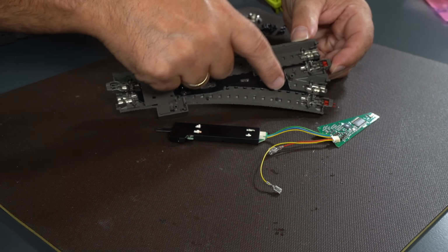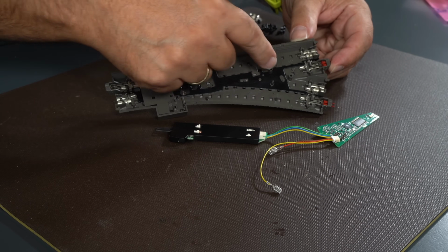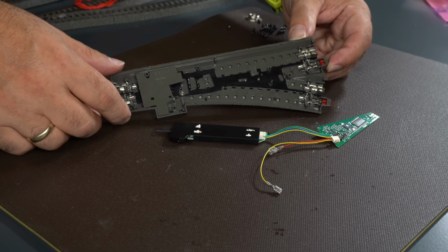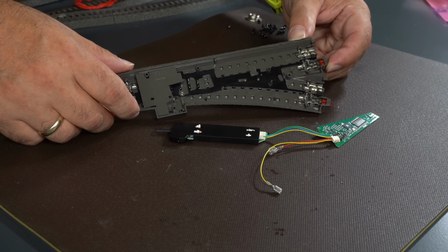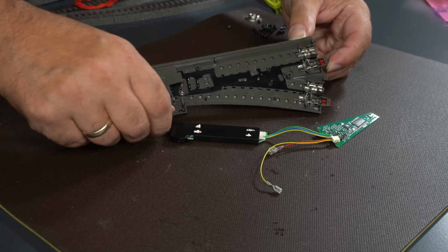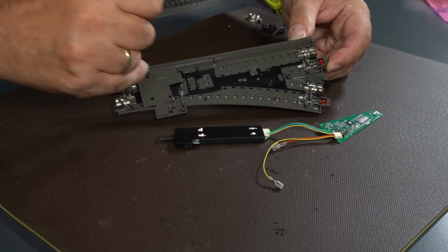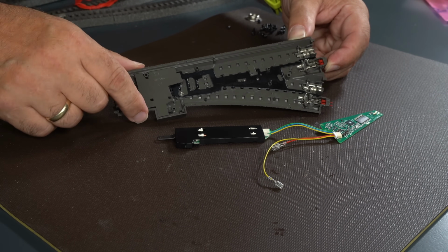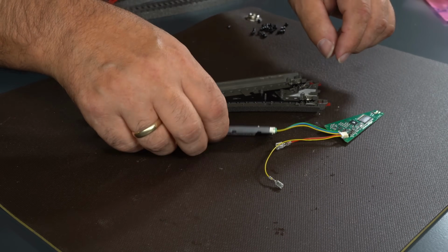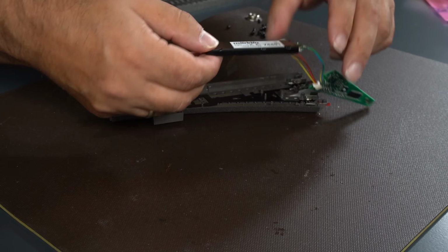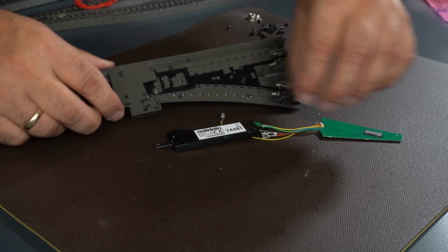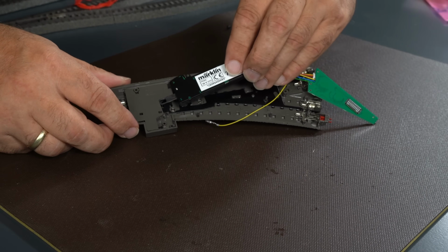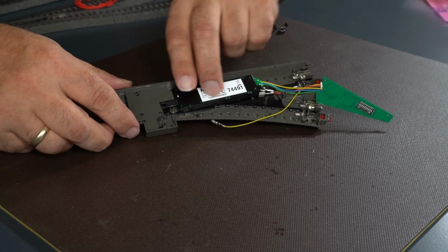Then after that, we have to place these two units, meaning both the power supply and the decoder, into the turnout, so to speak, ensuring that everything fits as intended. The corresponding mounts and screw connections, which are essential for stability and safety, are already prepared for this purpose. We just have to make sure, for example, that with the turnout drive, the tongue is properly positioned with the actuator of the turnout drive so that the tongue can actually be switched without any obstruction or misalignment. Yes, and then it's actually very easy to assemble, much easier than it might initially seem.